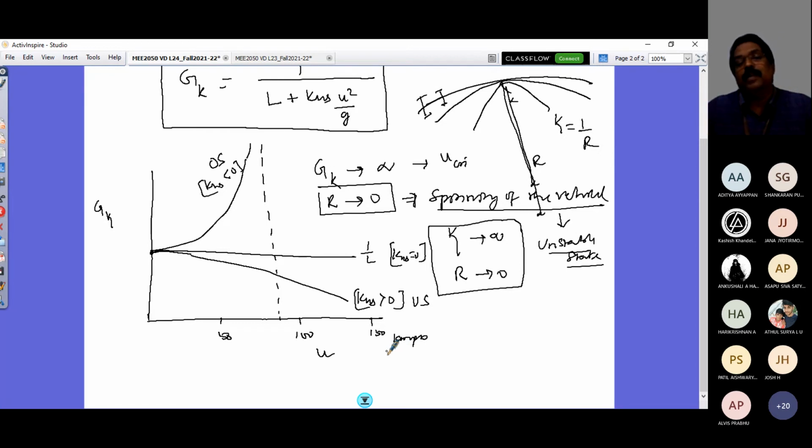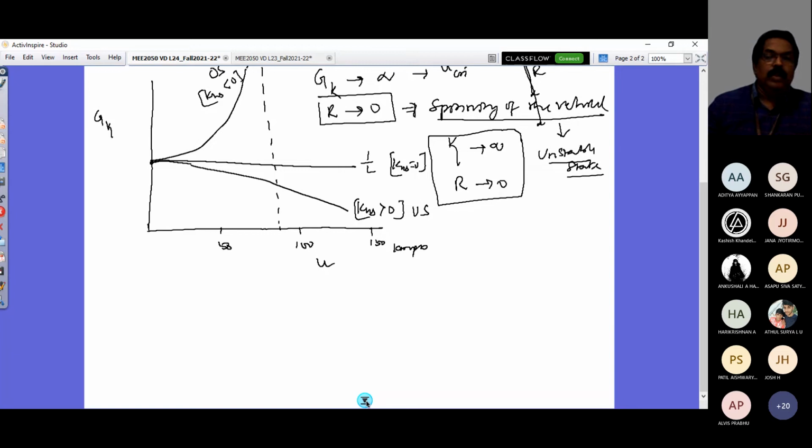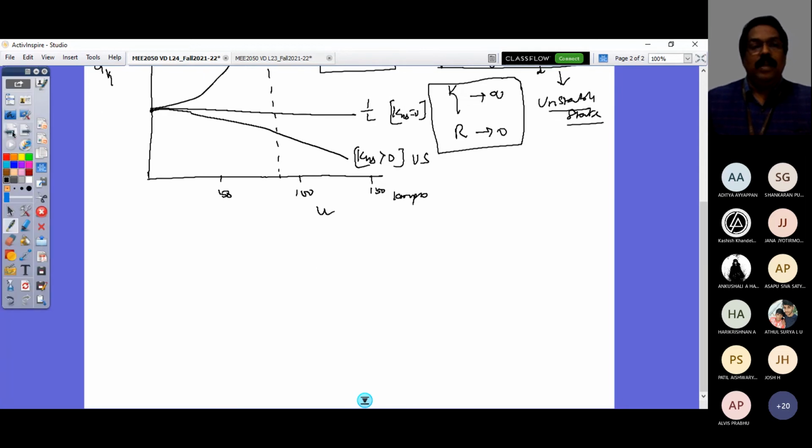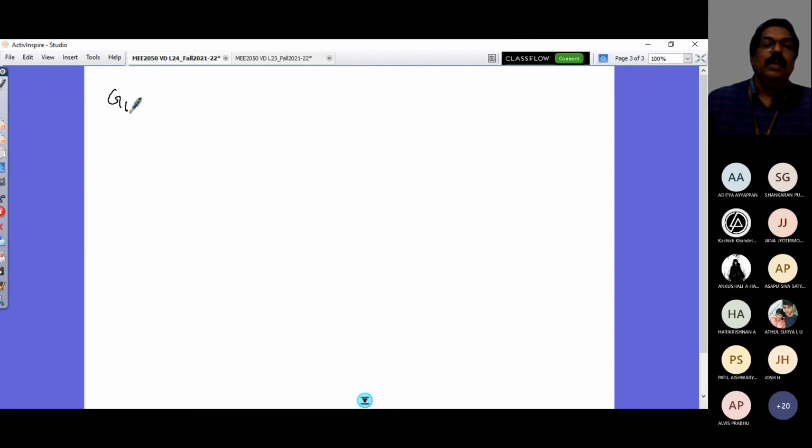I could compare the class of vehicle for different steady state conditions. So similarly, the third gain is the lateral acceleration gain. So that's G lateral acceleration gain. So that's going to be obtained in terms of this. So how do I refer to it? You can say that that's going to be lateral acceleration. So lateral acceleration is AY by delta as s tends to 0.